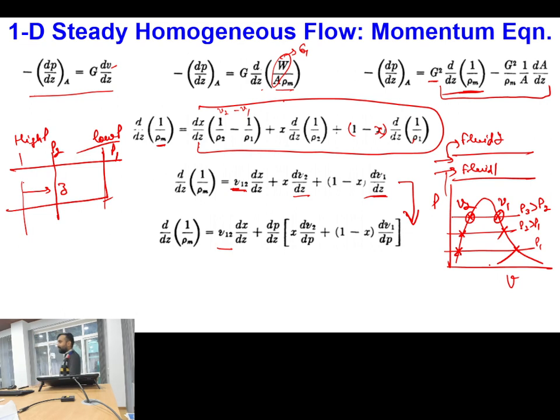So it means that in a two-phase flow pipeline where phase change heat transfer is there, you have the combination of a liquid and gas phase of a pure substance. When you are moving from one end of the pipeline to the other, as your pressure is decreasing, the thermodynamic state of the individual substances is also changing. Is this one clear or not?